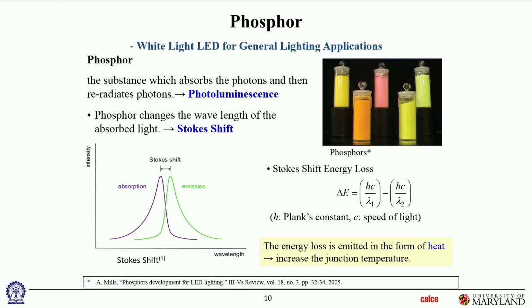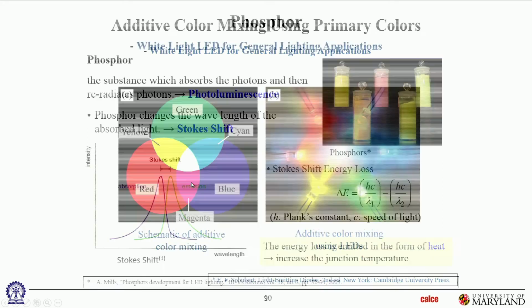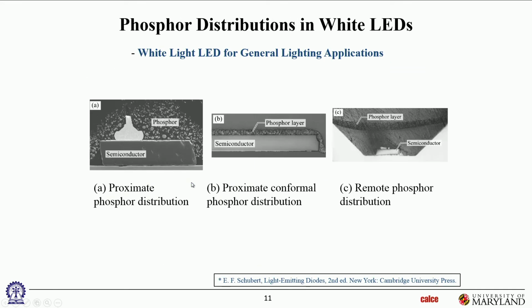Or you do this phosphor technology, where you cover your LED device, semiconductor device, with specially tailored phosphor layers. This is typically a blue LED, and the photons of blue frequency coming out here get absorbed into the phosphor layer. The phosphor absorbs it, gets energized, and re-emits new photons that are wideband spectrum, so it looks white.